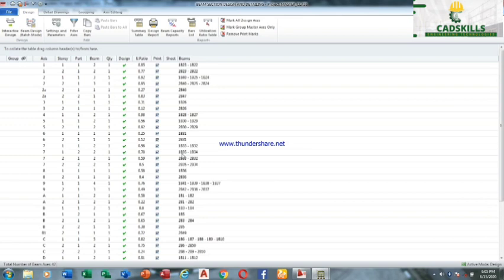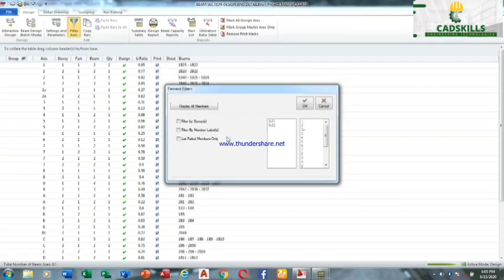After generating your load, your second floor, the last floor, all those beams, change them, highlight them one by one. When you highlight it, go to the beam icon, open the beam icon, change your 225 to 200, change your 450 to 225 or 300, update it. It's going to do all your beams like that, so that you will have 225 by 300 or 225 by 225 roof beam.